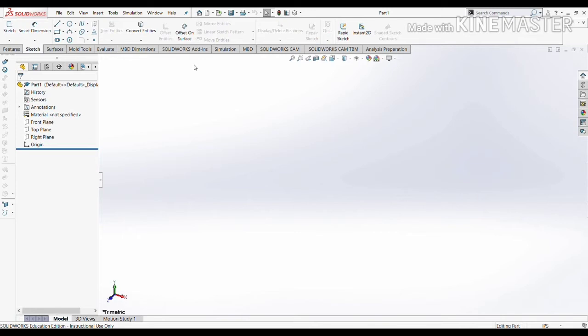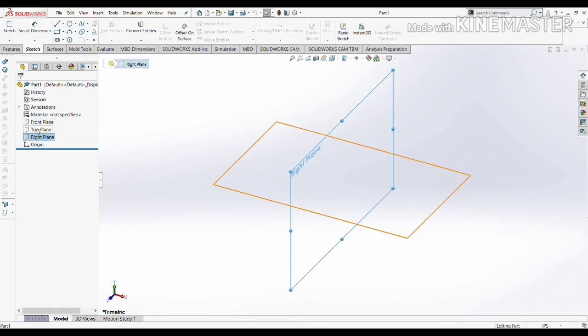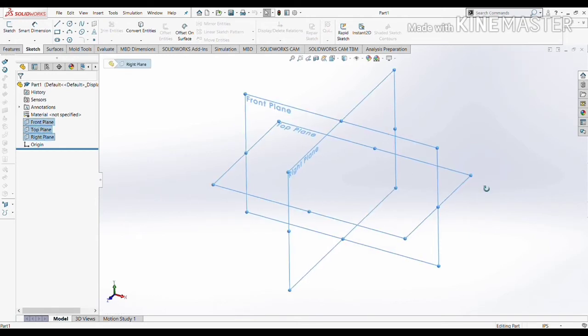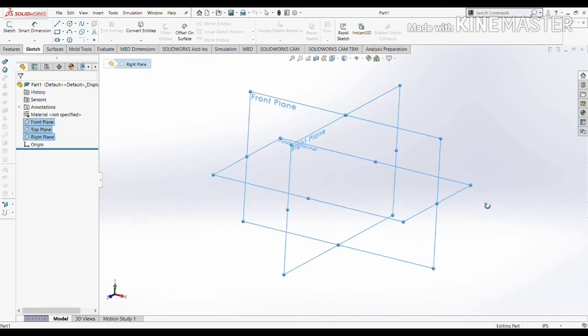Now, SolidWorks works by using a 2D sketch of a solid geometry and extruding it or cutting away using that 2D sketch. Now, to make a 2D sketch, you need planes. Every part has a generic front plane, top plane, and right plane in it, and you can see here how they hold up. And centered in the middle of those is the origin.